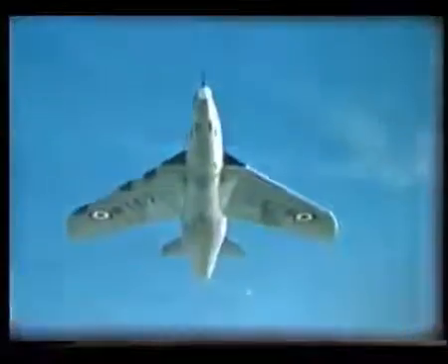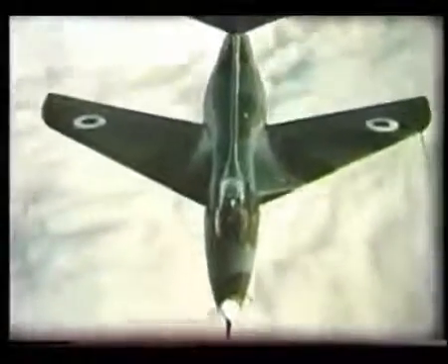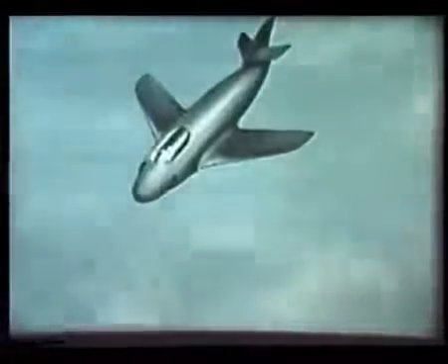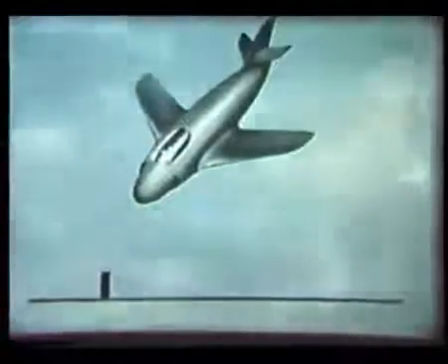Still, faster flying is only possible when wave drag can be reduced. The drag caused by the shock waves changing kinetic energy into heat. A new design principle helps to do this. Area rule. Consider this aircraft. Take a section through it at right angles to its axis. Now represent the cross-section on a graph. Do this at points all along the axis.